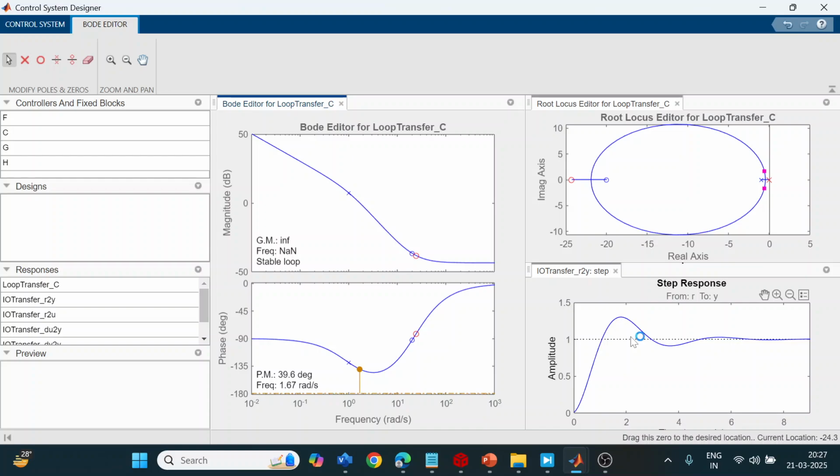Those parameters you can change, and accordingly you can reduce the peak overshoot. The dominating parameter will be only zeta. Do you have control over zeta, and how will zeta vary? Zeta is nothing but the cosine of the angle theta between the pole and the axis. Everything is related to your dominant pole.